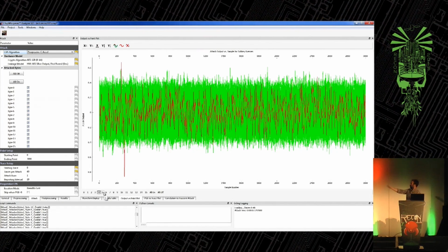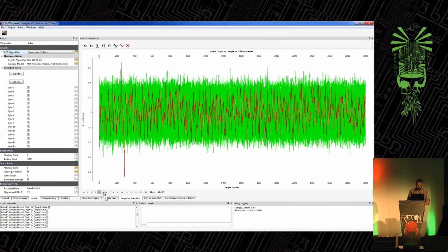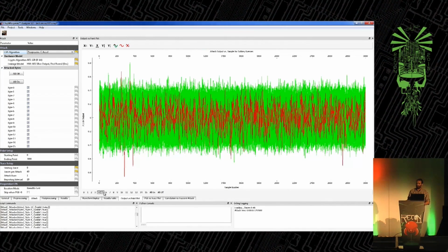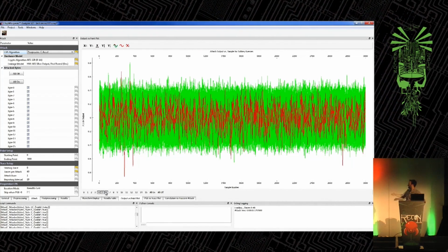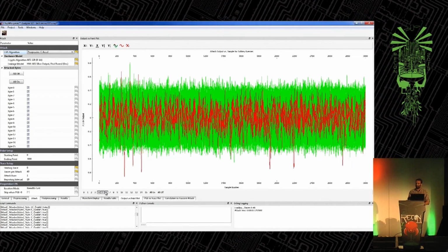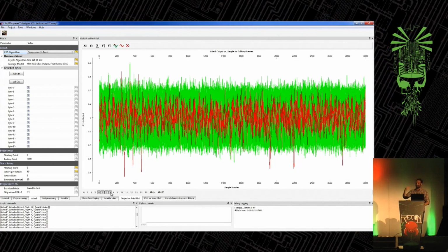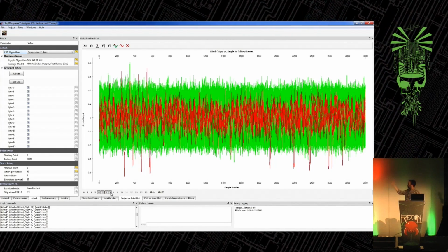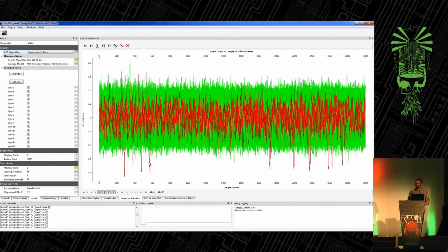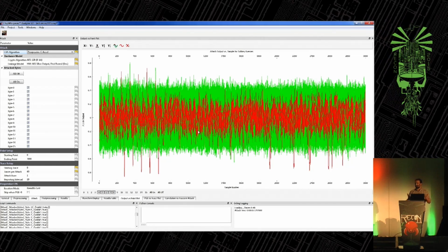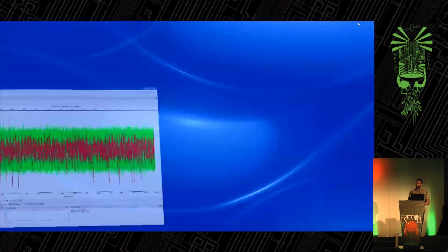So I can compare, for example, this is recovering byte 4. If I look at recovering byte 5, you'll see that the peak is marching on in time. This is because this is an AES software implementation, so it's doing byte 5, byte 6, byte 7. And you can see the specific instance in time where that operation of interest is occurring. So it also gives you some information about the underlying process. All right, so there's that.